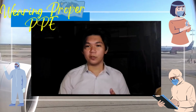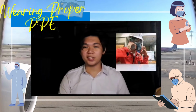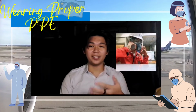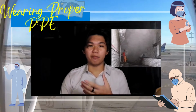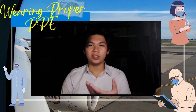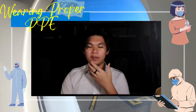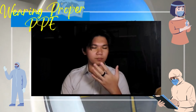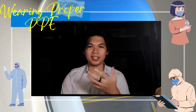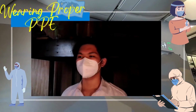Next, we have respirators and face masks. These are necessary equipment that is needed when being exposed to highly toxic gases. So for proper wearing of respirators and face masks, we must ensure that our equipment is well fitted onto our face with no signs of spaces and any crevices that the highly hazardous gases might get into and affect the person's breathing.